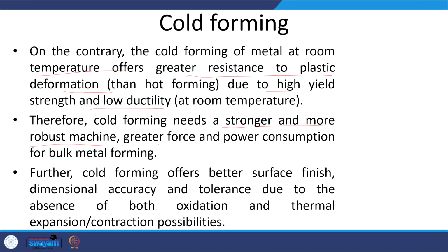Therefore, it needs greater force and power consumption for bulk metal forming. Cold metal forming has to handle metals of higher yield strength at room temperature as compared to hot forming for the same metal, and therefore it needs more robust machines, greater force and greater power consumption.